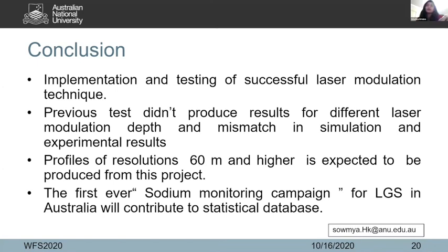Yeah. So the AOM which is used will be modulating the power of the laser according to the pattern we feed. It basically works like a Bragg cell. The refractive index of the system changes when an electrical pulse is sent, and that is basically on the sound wave. So yes, that's how an AOM works.